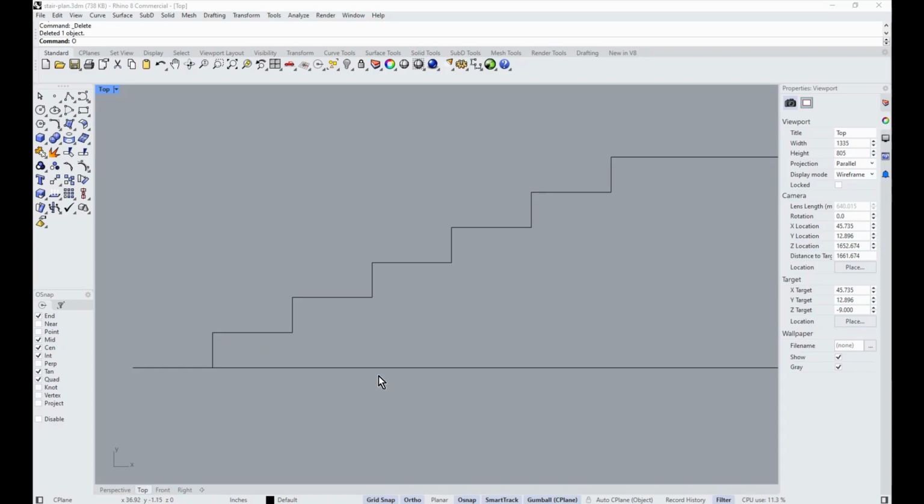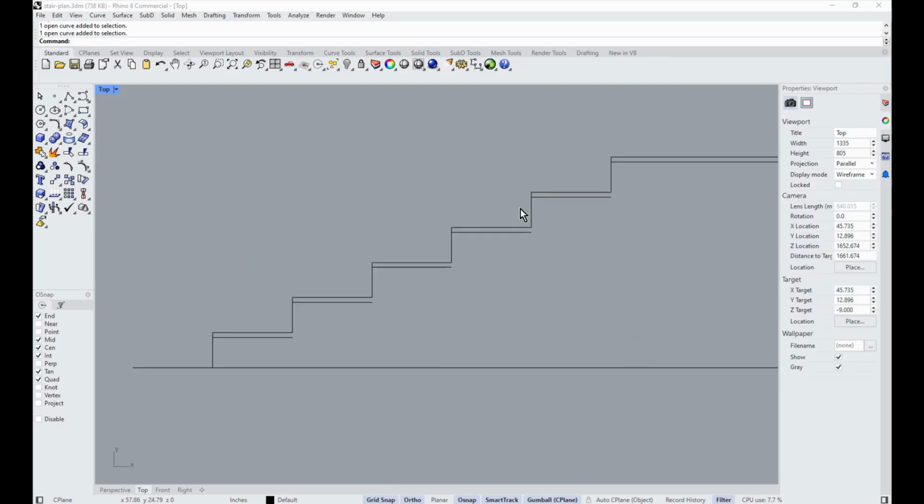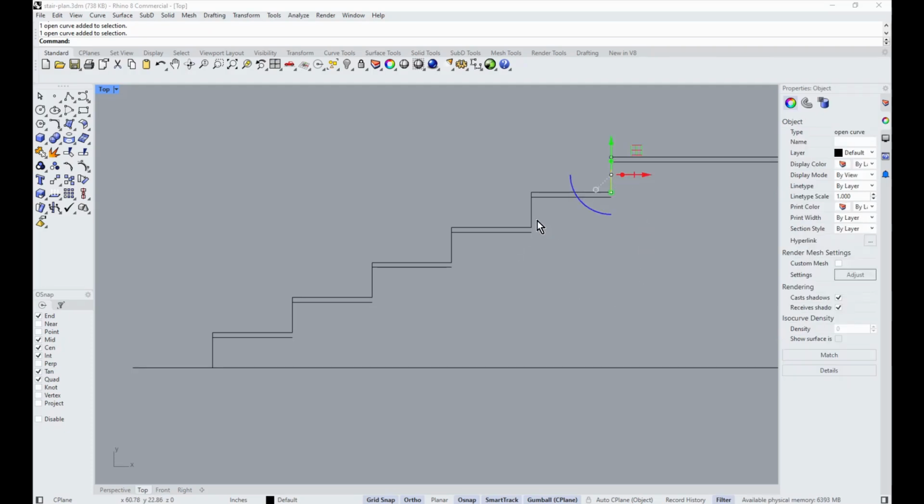And we'll offset those. Actually, I can probably grab all of them. So I grabbed all of them and we'll offset them down by minus 0.75. So that's your plywood right there, 3/4 inch plywood. This is keeping everything honest here. So let's see here. Next thing we've got to do is we're going to use 2x6s that are ripped for the risers.